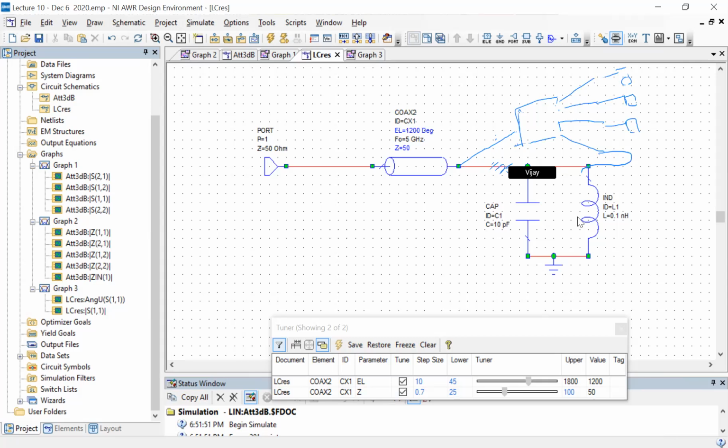So then in the same measurement cool down, you have to make sure that all of these lengths of the cable, everything is identical, so that you do the calibration properly. And there are switches like that available, we have them in our lab as well. And some people use this to do in situ calibration in a cryogenic environment. Okay, so this is not directly connected to microwave engineering in that sense, but it's a practical way of doing that. Okay, so then you can take care of this.